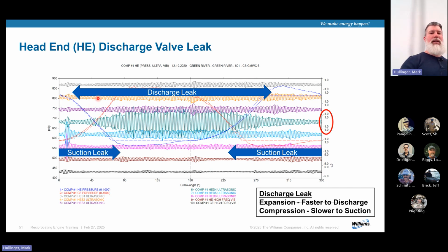On the other side right here, this is where a suction valve will leak if it's supposed to be closed. Look at that one right there. I mean, that's a nice football pattern, and that's discharge number 4, and it's leaking when it's supposed to be closed. So you're going to change that out probably. I don't have temperature right here, but if you put a temperature on that, or you put your hand up to it, you're going to say, hey, that one's hotter than the rest. So you don't even have to do this. This just confirms it.